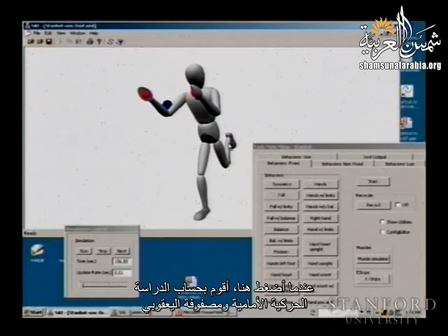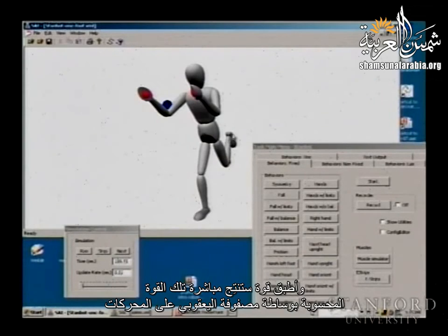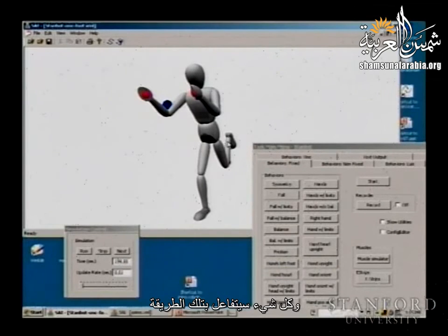When I click here, I'm computing the forward kinematics and the Jacobian, and I'm applying a force that is immediately going to produce that force computed by the Jacobian on the motors, and everything will react in that way. So we are able to create those interactions between the graphics, the kinematics, and apply it to the dynamic system, and everything actually is simulated on the laptop here.